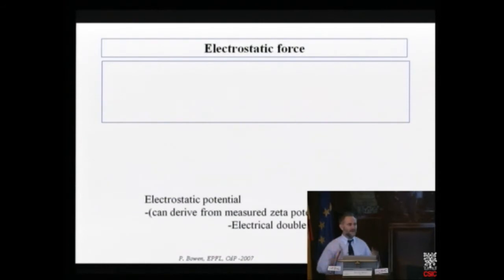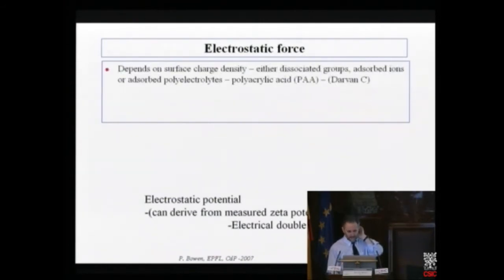The attractive forces depend on the dielectric properties of your medium. Okay? Electrostatic force depends on the surface charge density. We can have dissociated groups or adsorbed ions. We can have adsorbed polyelectrolytes like polyacrylic acid, which is the main component of Darvan, our classic ceramic dispersant.